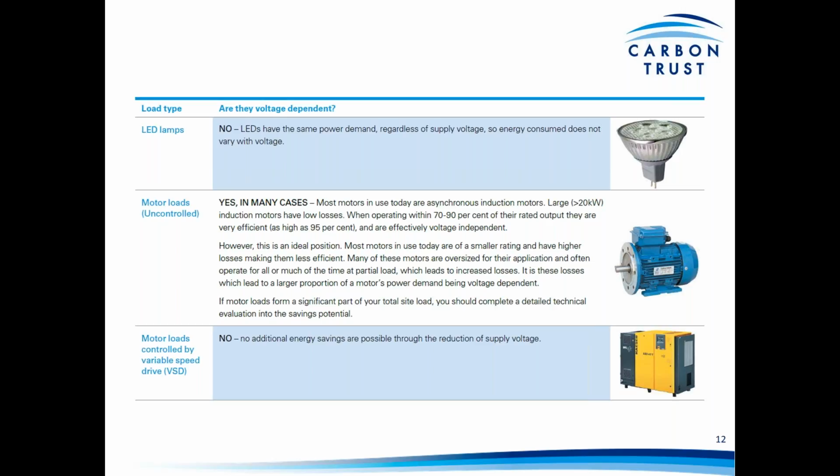So if motor loads do form a significant part of your total site load, then we would suggest a fairly detailed technical evaluation of these motors to see if there is any savings potential, both in looking at adjusting or upgrading the existing motors, or potentially in applying voltage management techniques to these.